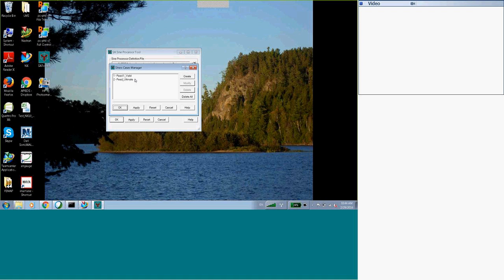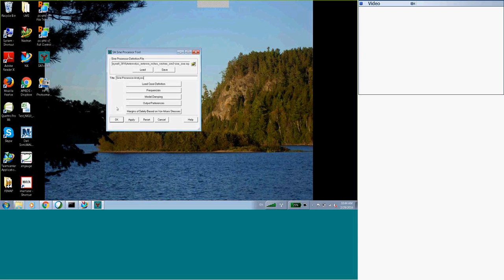Yeah, you just create more stress cases, and then for a group, you define a different material level. I mean, it doesn't store the ultimate strength and the yield strength in the MAT card. Otherwise, we could go directly out of the OP2 file. You know what I mean? Yeah. Okay, so I've done that.